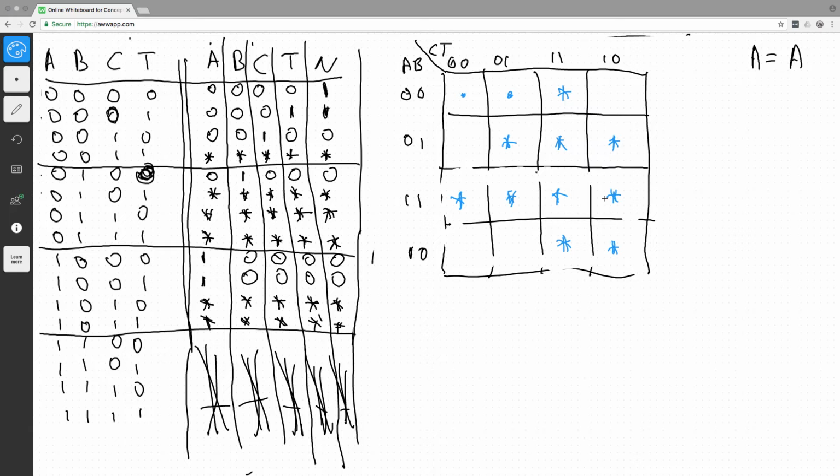Now let us see how we can optimize this. Unfortunately, the B signal is not that good for optimization, because if we want a cluster to surround both of these, that is the largest cluster. It has to be either along one dimension or the other, but we cannot utilize any diagonal elements. And it has to be of the size 1, 2, 4, 8, 16. So that is the largest cluster we can form.